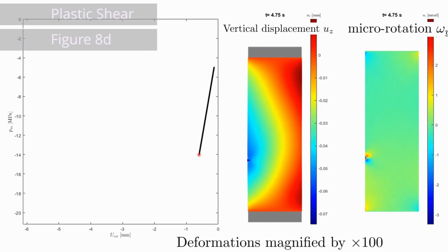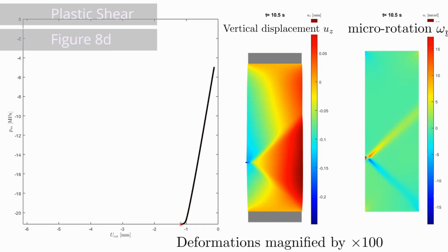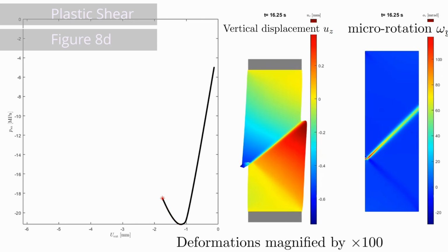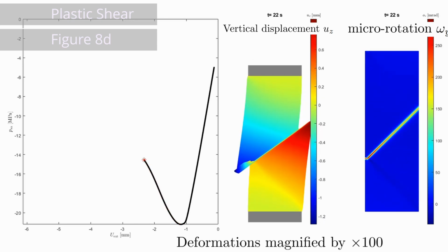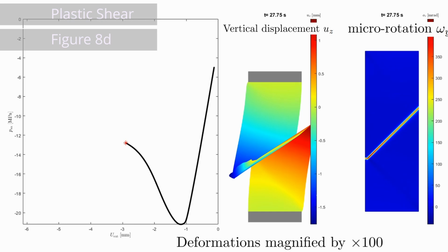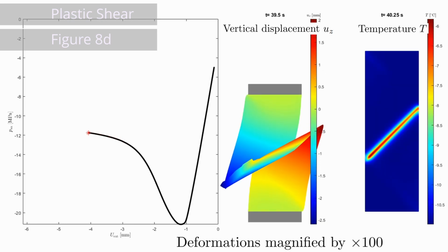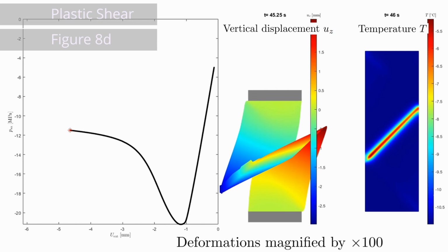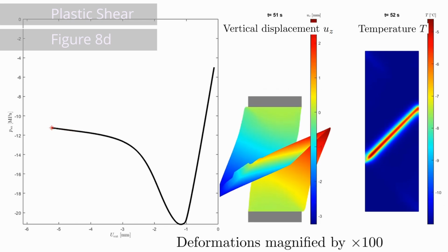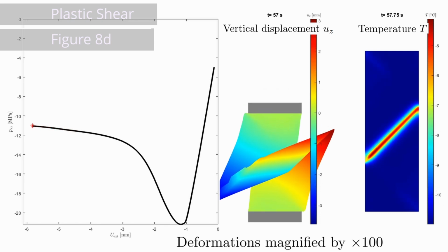Temporarily increasing the tensile strength of the ice to suppress cracks, we can investigate the mesh dependence of the plasticity model. A Cosserat continuum is used to regularize the shear bands, spreading them over a finite thickness. We can also look at the temperature changes happening at the shear bands, with the plastic dissipation causing several degrees of temperature change during the plastic failure.